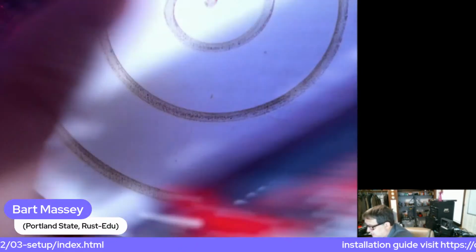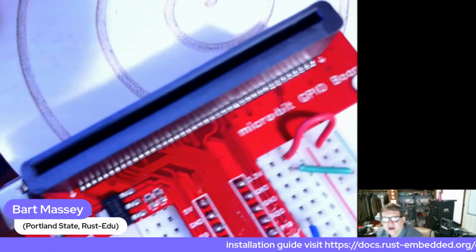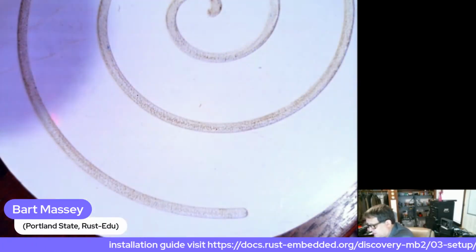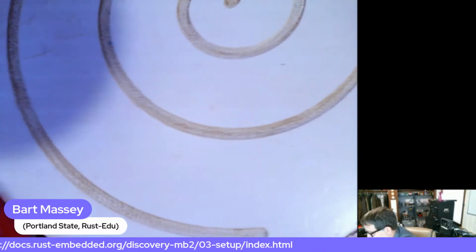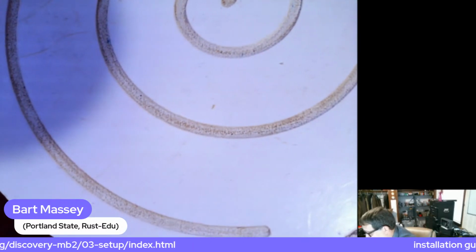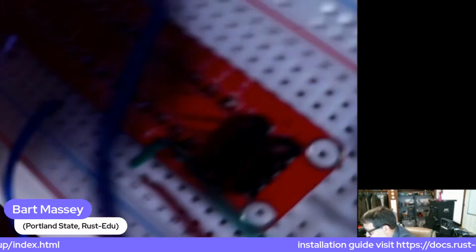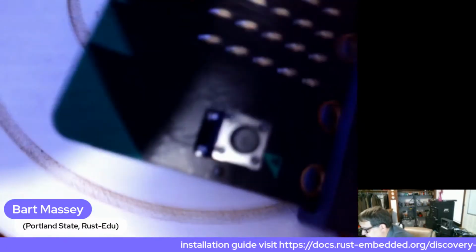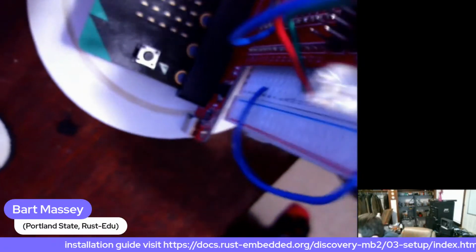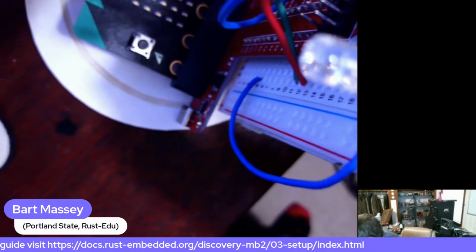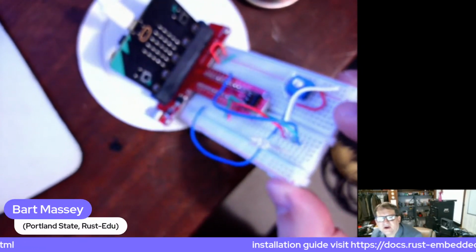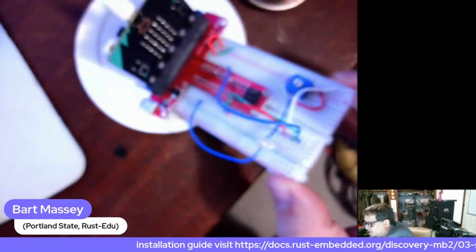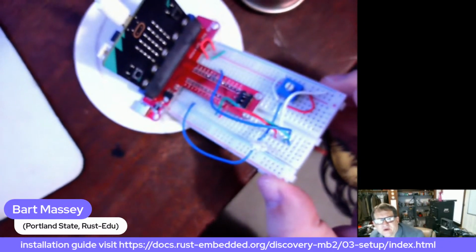This little black thing is an edge card connector, and I can actually plug the board right into it. Let me do that for a second, but let me turn it off first, because always power off things before you plug power onto them. Now, let's see, I think I can show it like this probably. Now, if you look at this, no, still not high enough. We'll go higher. You can see that I've plugged this board right into this edge card connector. And yes, it matters which direction the board faces. If you turn it around, it won't work.